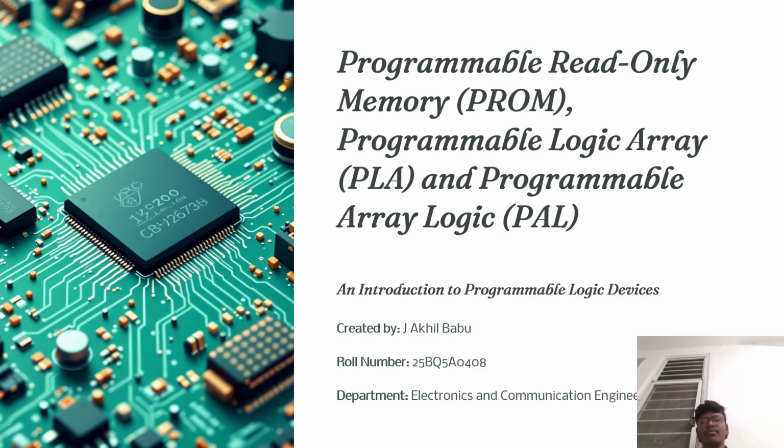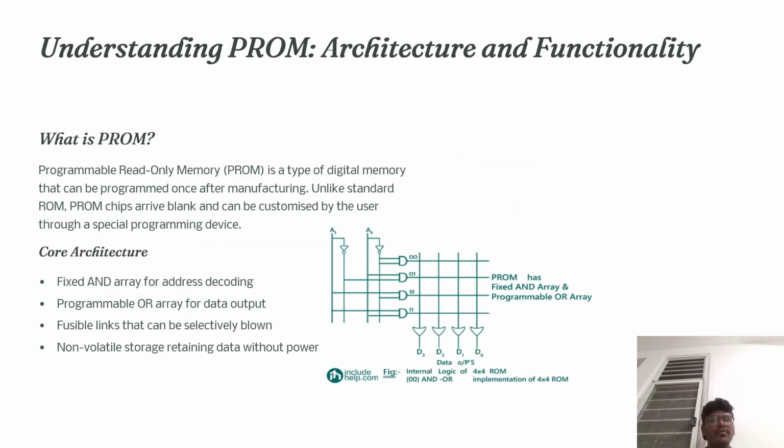Today I will talk about programmable read-only memory, programmable logic array, and programmable array logic. The shortcut forms are PROM, PLA, PAL. And an introduction to programmable logic devices. Understanding PROM architecture and functionality.